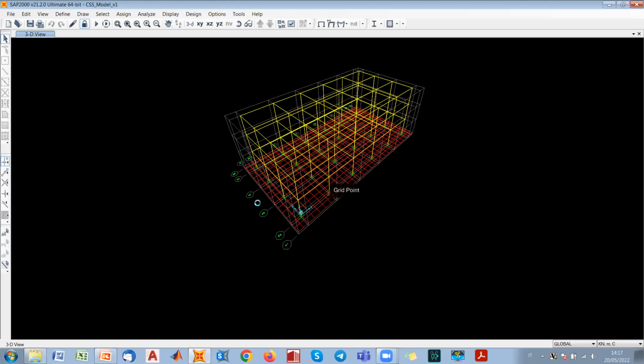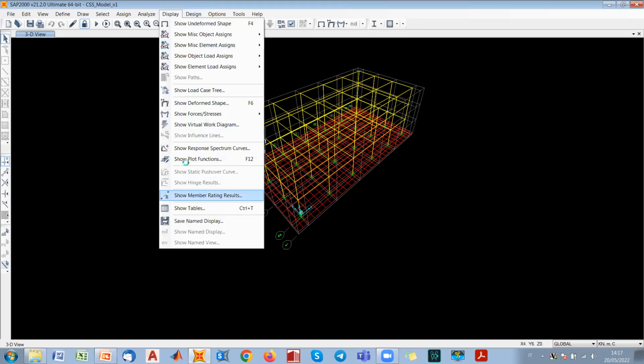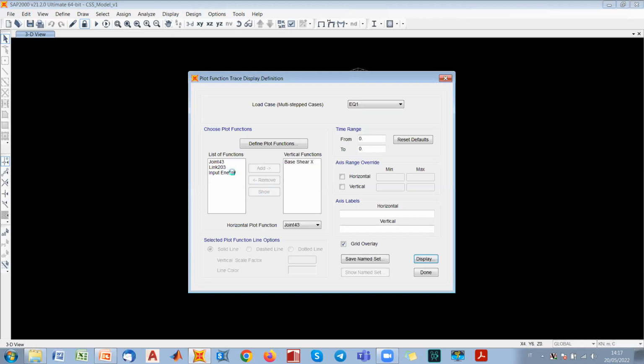But locally, all the isolators are subjected to variations of vertical loads, and so the main result that we get is what we have seen, like in the example for the corner isolator here. So a fluctuating horizontal response as well as the vertical one. So we can also have a look at all the other hysteretic responses. So let's say, okay, again, base shear. Let's remember that there is a minus on the vertical axis.